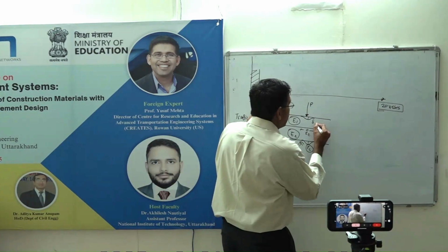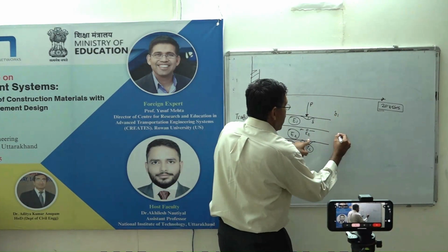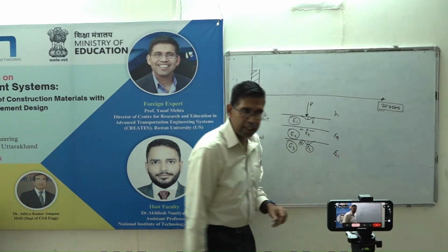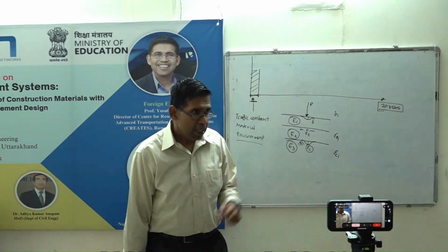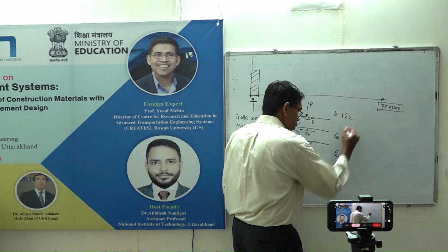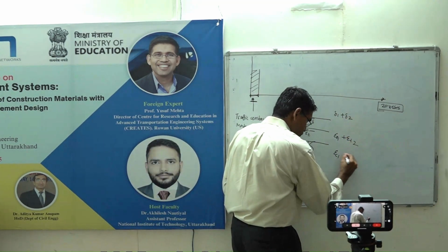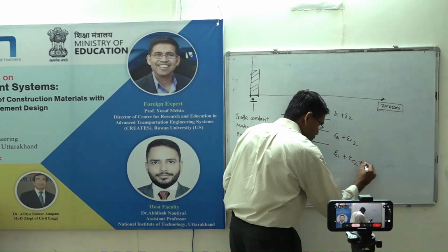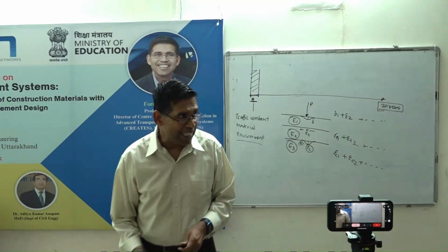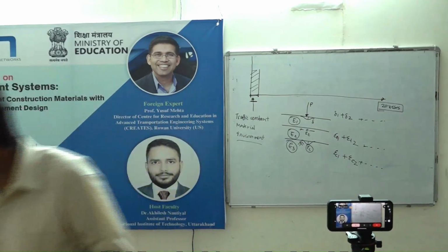Then you calculate delta 1, epsilon T1, epsilon C1 for the first 15 days. Everybody with me? Now the next 15 days come. Add them up. Another 15 days come. Add them up. Add them up. Everybody with me so far? That's exactly what this is.